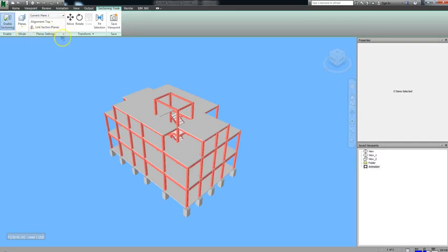When you're in Planes mode, the next panel over, Plane Settings, lets you determine what type of properties apply to your planes. You can choose different planes, and then you can assign different properties to them. So for instance, you can choose whether the planes align at the top, the bottom, front, back, left, or right, as well as where on the model the plane will align to. Either the surface of the model, or a line that you can draw.